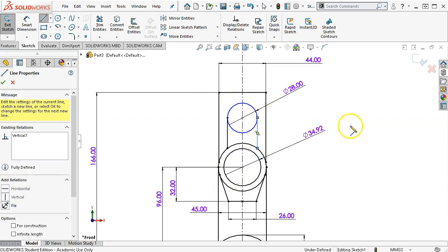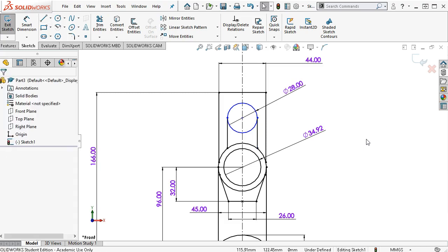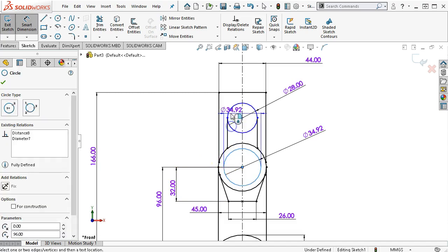All right, and then the through hole, we're given an M12. Let's just stay with the 12 millimeter on this one. If we put the hole wizard in there, I'm looking ahead as far as what's going to affect our mass properties.